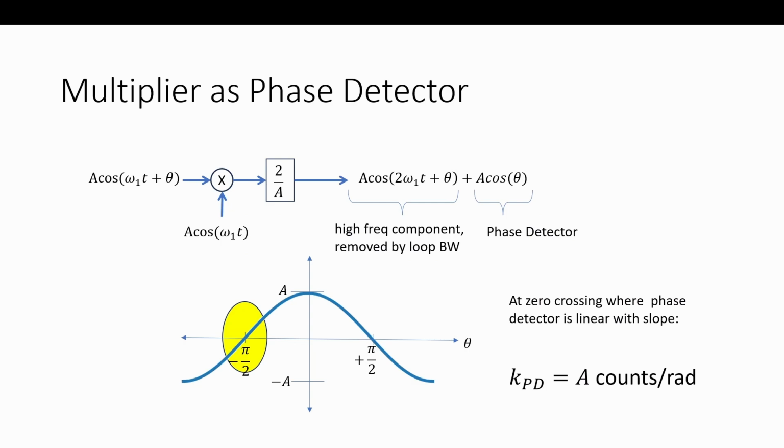So again, just keeping track of units, being careful with units, you get the right values. That's the bulk of the work in making these loop models. Extracting these things. What do they do? When I change the input, how does the output change? And again, does that output have any dependence on frequency anywhere near where we're operating? No. If it's instantaneous like this is, then it's just a simple gain, the slope of that transfer function. Phase going to magnitude. That phase error here, I have a magnitude coming out.